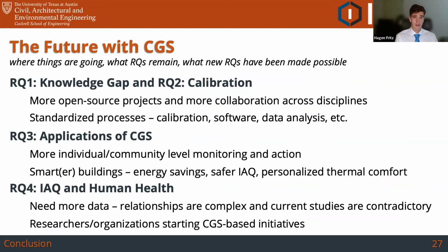If you take a classroom that's not occupied for 4 hours in the morning, you don't need to ventilate that space. So if we can do some occupancy detection with things like CO2 and TVOCs and we don't notice anyone there, we don't necessarily need to cool it down as much as we might other spaces. Now, when that classroom starts to get occupied in the afternoon and we start to see more and more people in that space, then we can start to ventilate it more.